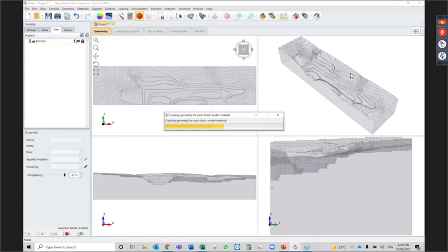And now our 4 material types are defined using the block model import file. We can now go and add additional features to the model, such as new materials or weak planes to compute a factor of safety. This example is in the tutorials and has just under 3 million blocks at block spacing of 3.7 by 3 by 2.1 meters.